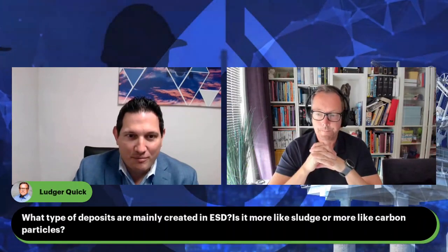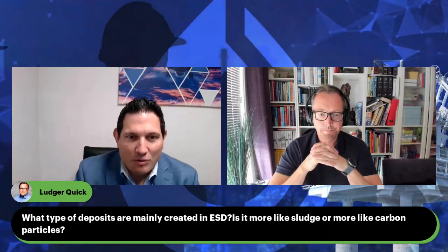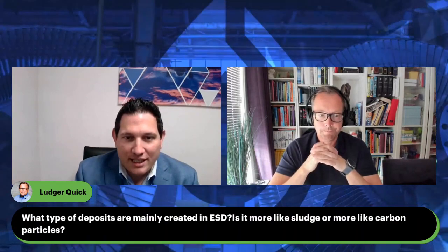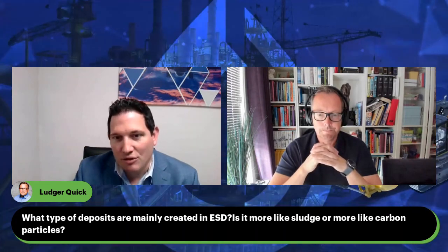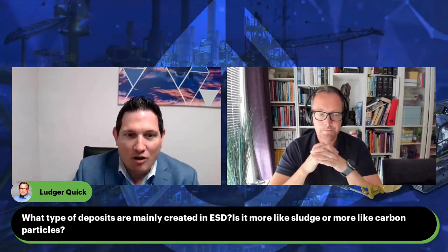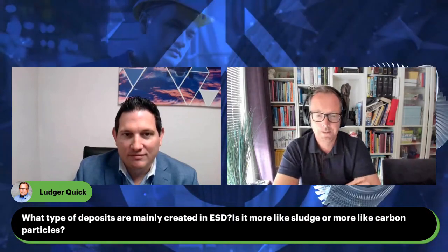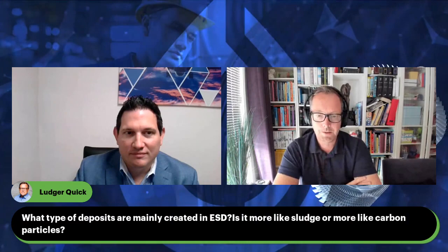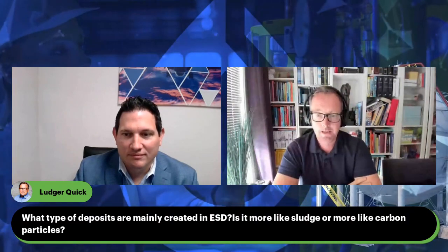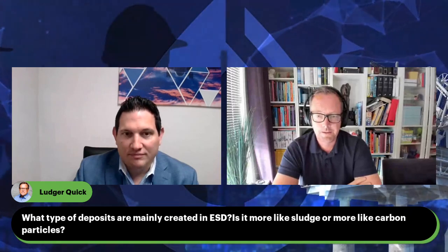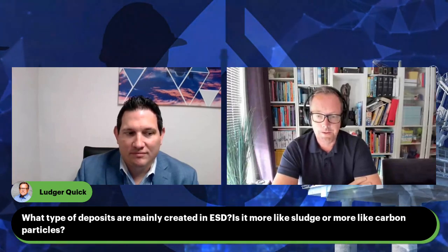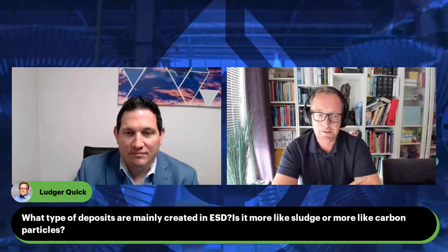Got it. And we have a question from Dr. Quick. What type of deposits are mainly created in ESD? Is it more like sludge or more like carbon particles? Yeah, what we've seen is the typical sludge buildup in the coolers, and of course in the bearings you get more of the carbon lookalike particles.